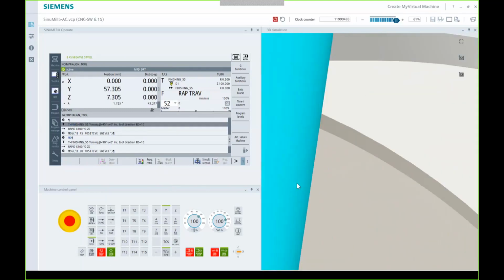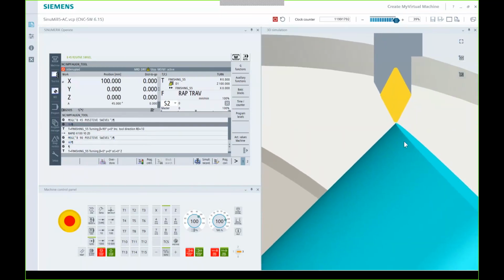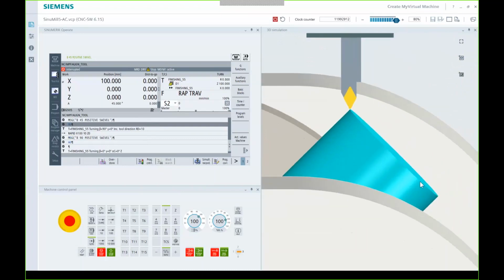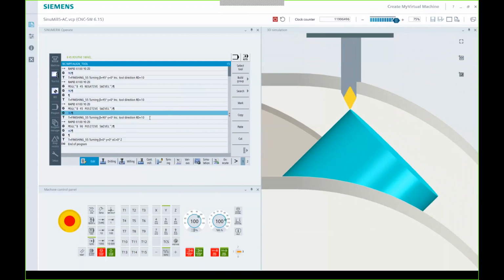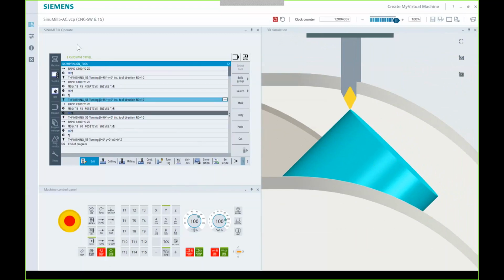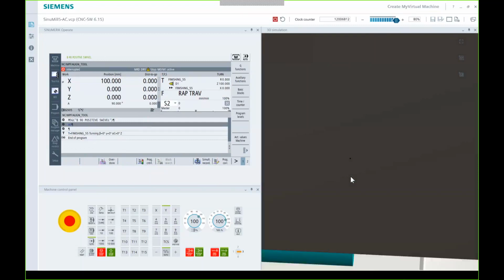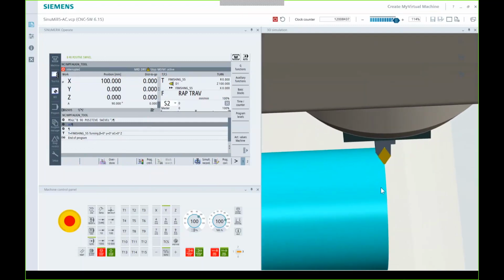Then I come over here, I'm rotating on the other side, and I'm coming back over this side. And these are all positive x-axis moves. The way I got it to the other side was that position negative, position positive that you saw inside the cycle here. This rotates which side of the part. It's going to rotate your A, but it's still going to consider it a positive rotation. So then if we come back over here, we go back down, now we're at the 90 degree. Kind of hard to see because of the machine.